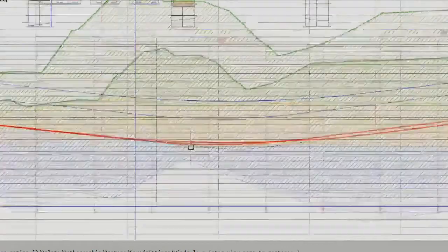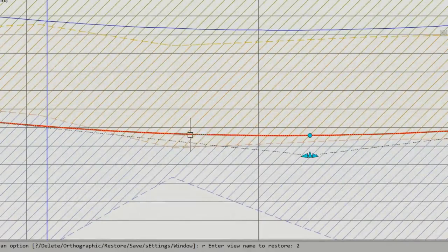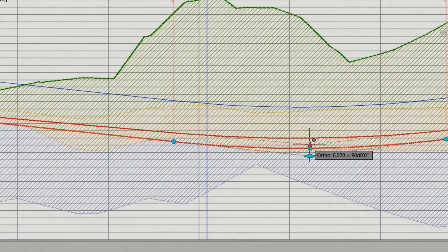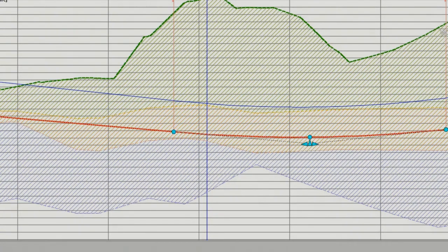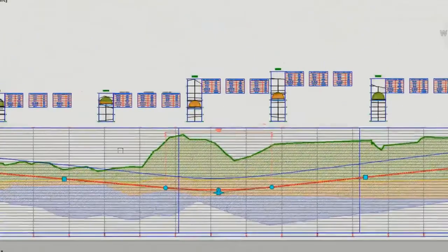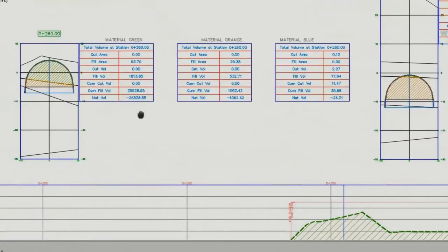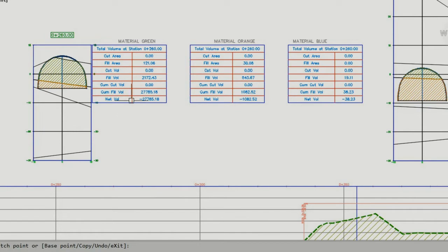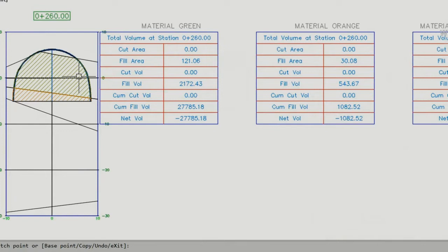All right, now what's the magic about this? If I move the tunnel, what's going to happen to the cross-section? It better change, because that's one of the principal fundamentals of a good BIM model. It has to be dynamic. So let's see if this actually worked. I have to hit rebuild the corridor, and you'll see it snap. See it snap? Okay, so now I raised it up high enough so I don't have any blue. I'm out of that strata zone.